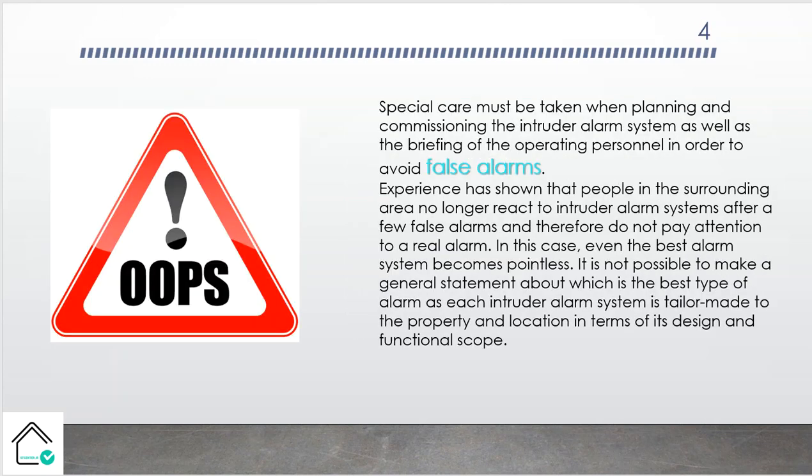Okay. Special care must be taken when planning and commissioning intruder alarm systems, as well as briefing the operating personnel, in order to avoid false alarms. So please note that it is very important in your security systems to not have false alarms. Experience has shown that people in the surrounding area no longer react to an intruder alarm system after a few false alarms, and therefore do not pay attention to real alarms.